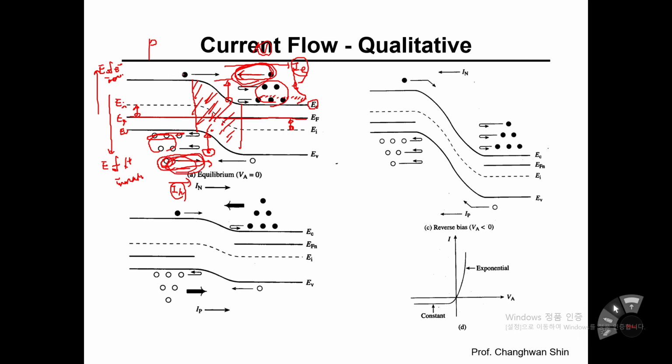So we should imagine what kind of electron and hole movement cancels out this movement. The answer can be found in how the minority carriers, instead of majority carriers, are moving into the other side. So this is the p side. The minority carrier is definitely electrons. So a very small amount of electrons, existing near the edge of the depletion layer width, would move to the left-hand side or right-hand side, if I limit the space to a one-dimensional space.